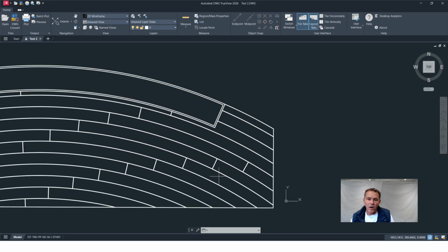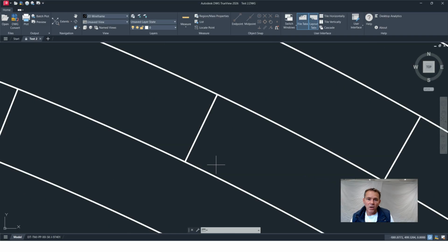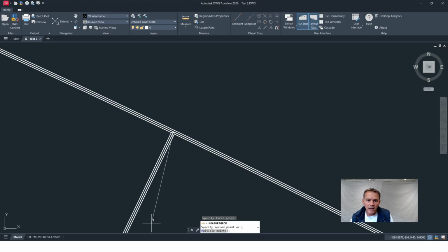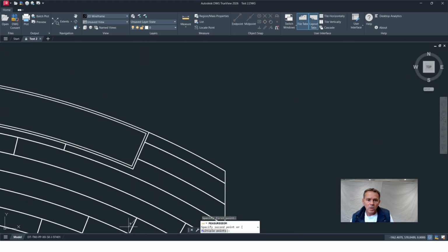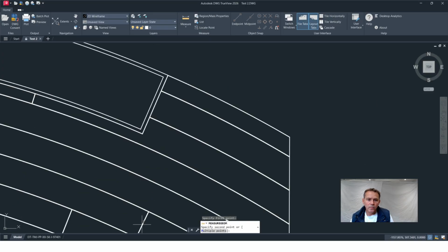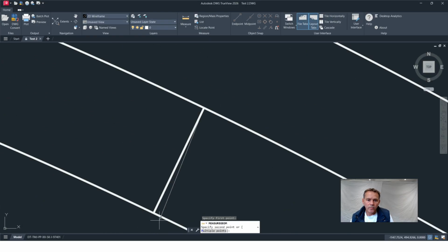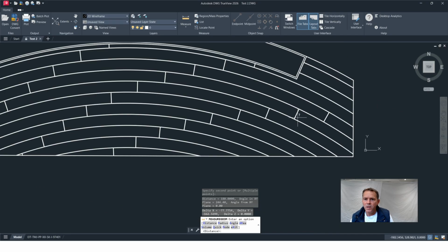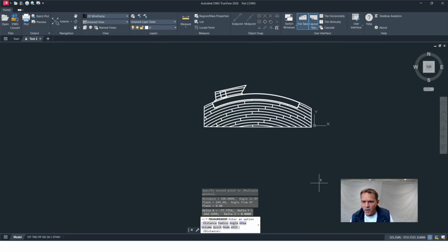It might be a good check, just to make sure it's scaled up correctly. I happen to know that these planks are 180 millimeters wide, so just find something that you can measure. So let's click on here and click on down here, and we should see, there you go, distance 180 millimeters. So pretty confident that's come through at 1:1, and we're all happy with that. So let's close that out.